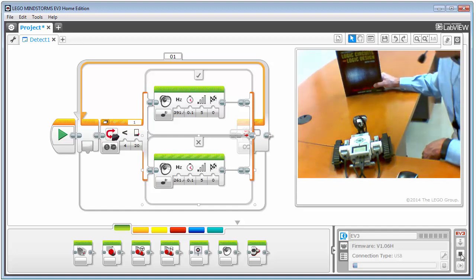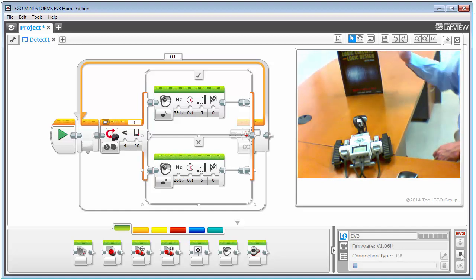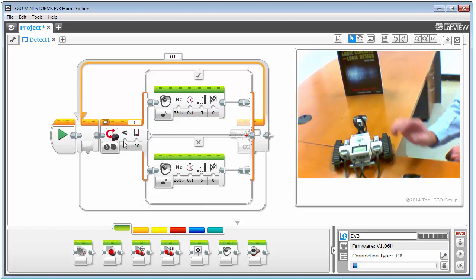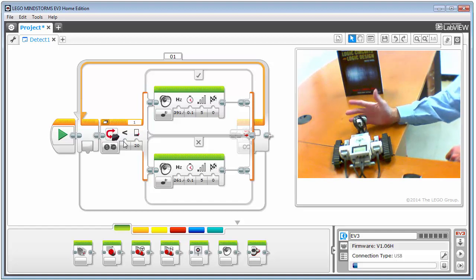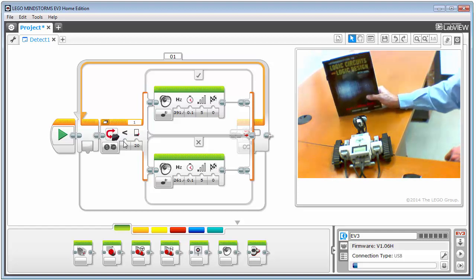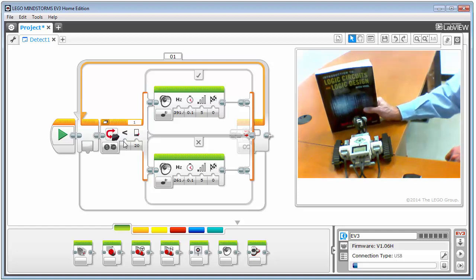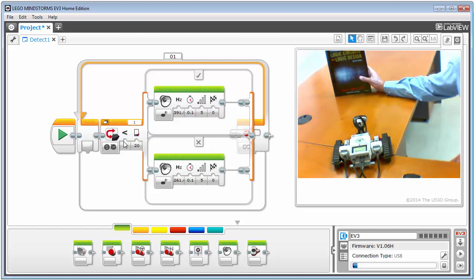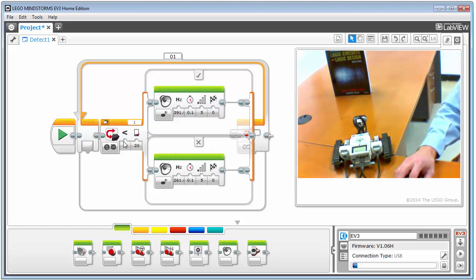So we did it. We've actually figured out how to use the IR sensor, or ultrasonic sensor, to detect an object within a proximity. So we were able to say, okay, I know that something is within a certain proximity, and I know when it's farther away than the certain proximity, and we use that in a switch or a decision construct.